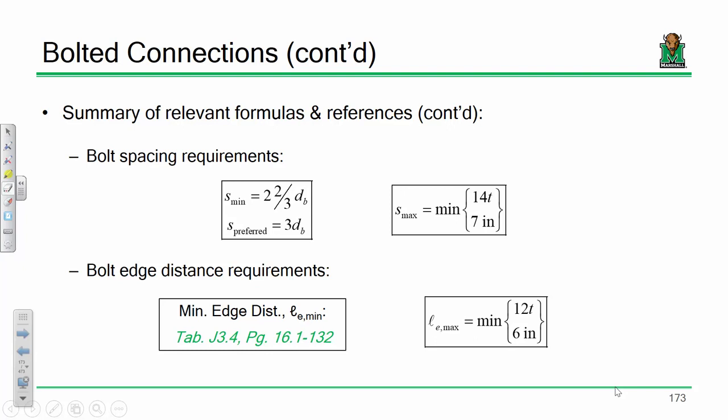In design mode, I actually sort of ascribe to the philosophy that the minimum diameter actually works pretty well. If you're using a 3/4 inch bolt, the minimum bolt spacing actually computes out to be 2 inches. So it actually works out as a nice round figure.